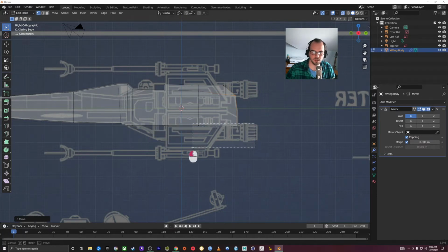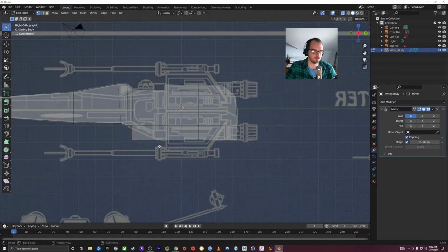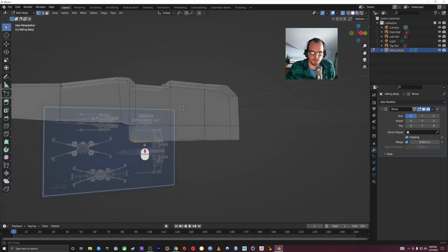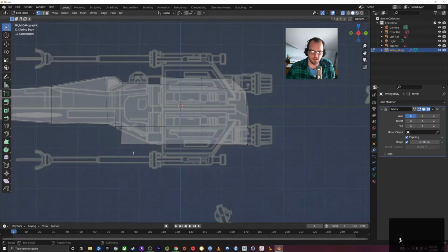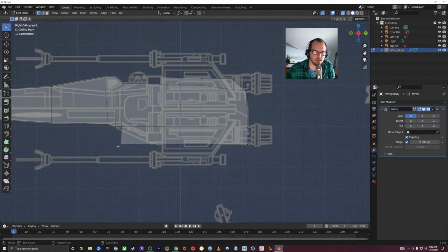And then also it looks like it comes down here at the bottom, that there's kind of an undercarriage. So I'll grab these here, and actually maybe just these ones. I want to include that little bit there. I'll extrude again here. Here's another tip actually. This is a useful tip. So looking at here, this created a rectangle where I want a square. So ideally I would want to delete these vertexes, so it was just straight across like this.